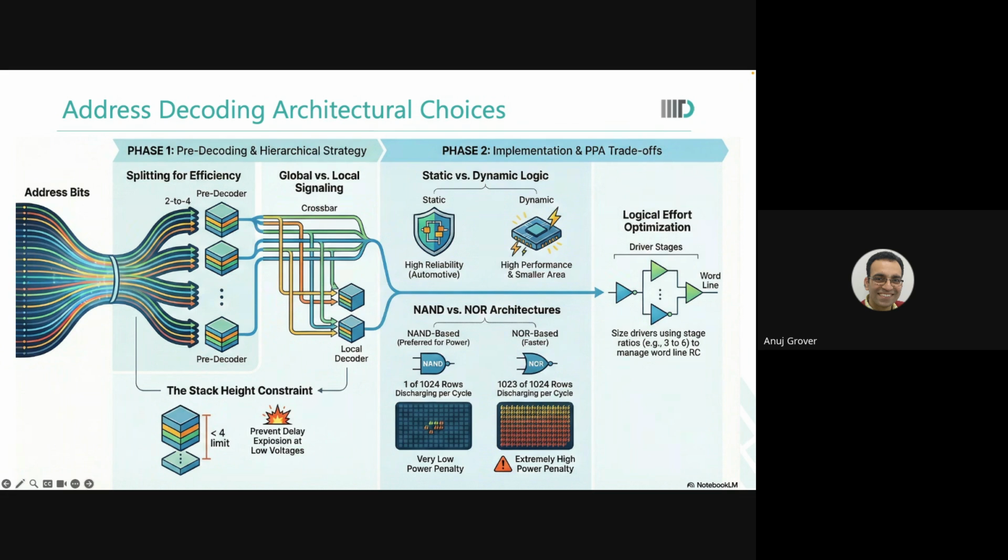Now suppose you said my LSB is used to select the column address bits. Then what would happen? Then what we have already seen earlier, word 0, word 1, word 2, word 3 will be adjacent to each other physically also, in the number of mux that you have. If the mux is 4, then word 0 to word 3 will be together, and word 4 will go to the next row.